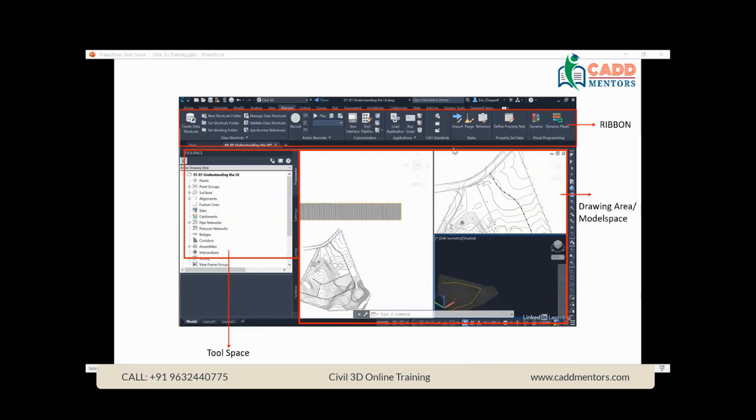And the Annotate tab is all about how you represent the data. I'm trying to give only a brief overview now. When you get into each thing, we will better understand how each one is useful. Let us say you have a point here, and it should have a text. How do you represent its elevation? For those elements, Add Labels will be useful. And Modify is for when you have made some alignments and designs and want to make some edits on your model space.